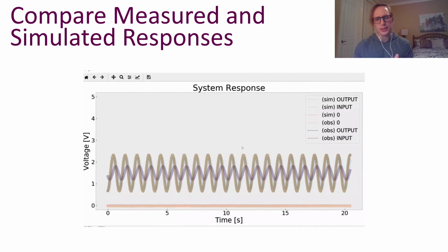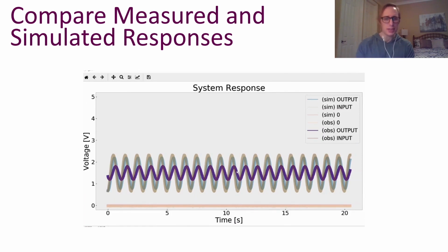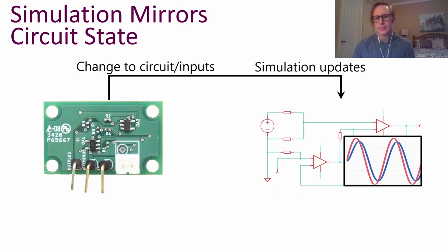With one command, Pinpoint takes measurements across the full circuit and juxtaposes them in an interactive plot with the responses to the same live input as predicted by the simulation. So we can see here how our physical circuit's output, that's shown in purple, differs from the simulation, shown in light blue. Pinpoint also makes it easier for me to make changes to my physical circuit and its inputs, and when I do so, the simulation updates in parallel so that I can continue to compare behaviors.